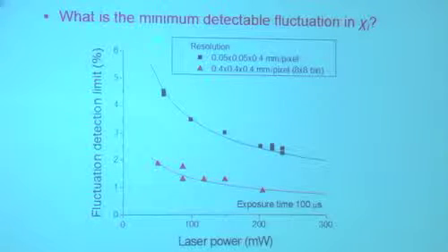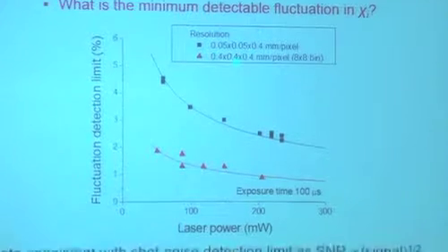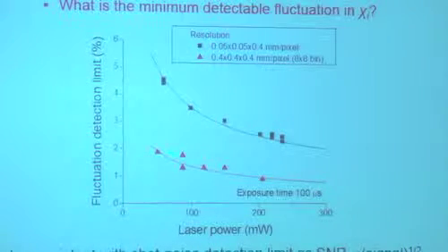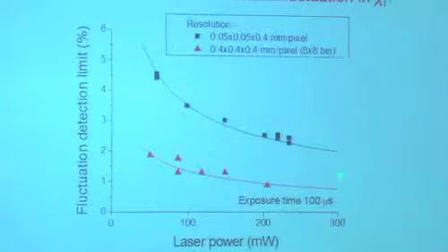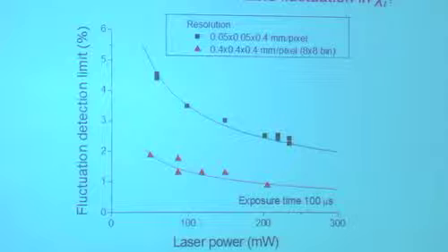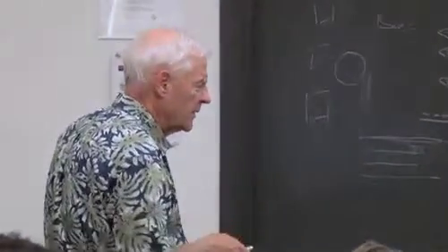And so that's the signal, this is the detection limit in percent. If you go to 400 microns by 400 microns by 400 microns, you get detection limits that when you have our maximum laser power, our detection limits are like 0.5% of toluene. So already you're beginning to see that means we could probably look at mixing and measure changes of about 0.5%.